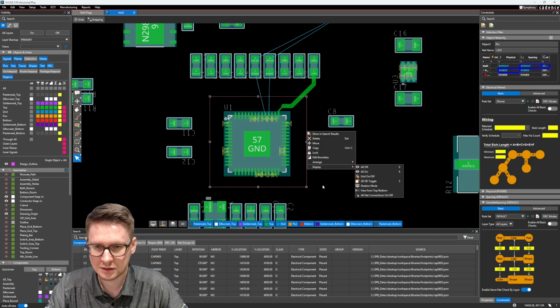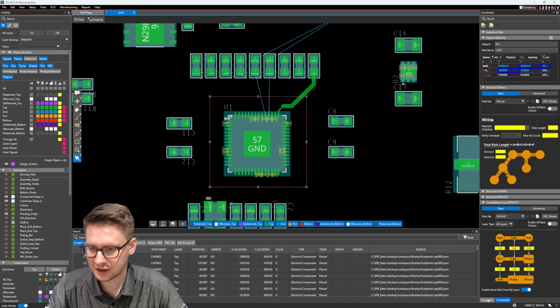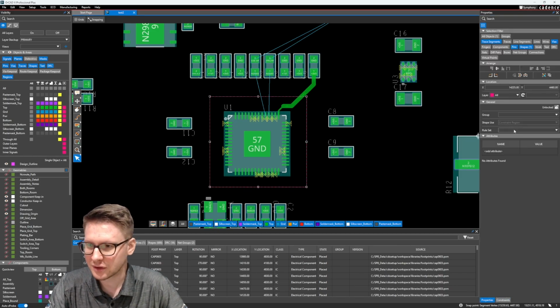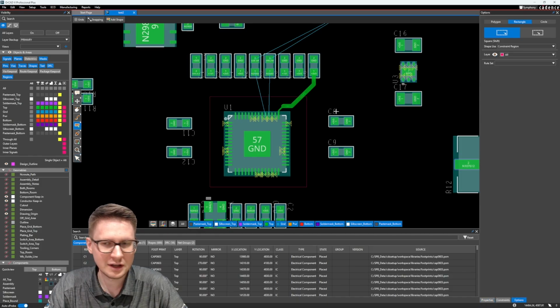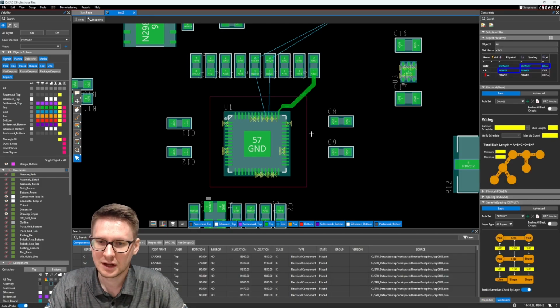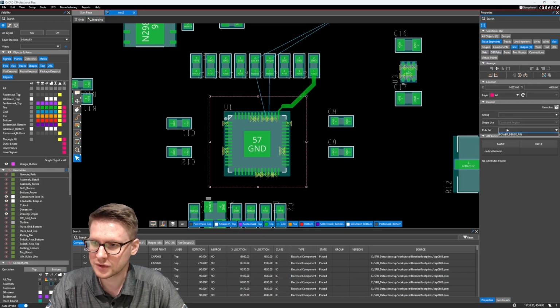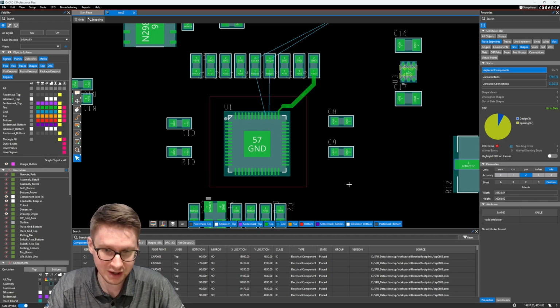And I forgot to set the actual rule set. So when you're in the command, you can set which rule set you want to set it to. So power dense pin, or after the fact, you can select the region, go to properties, rule set, and select power dense pin. And when we do that, you'll notice that right away, all of those DRCs have disappeared.